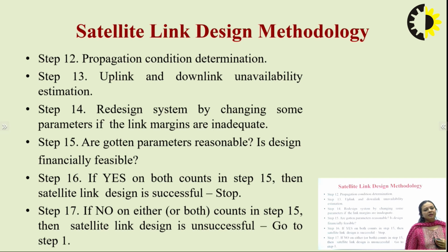So their unavailability estimation. Then redesign the system by changing some parameters if the link margins are inadequate. Then whatever parameters you have calculated, are they reasonable? Is the design financially feasible? If yes, then it's perfect. You have designed the satellite link successfully and you can just stop now. But if you got no for any of the answers in step 15, then the satellite link design is unsuccessful. So you have to start the procedure right from step 1.